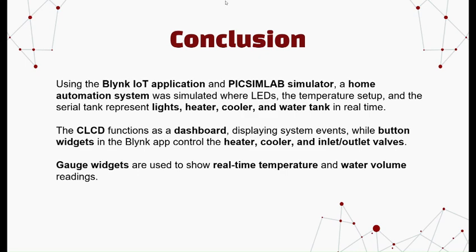And by the way, the conclusion is using the Blynk IoT application and PICSimLab simulator, a home automation system was simulated where LEDs, the temperature setup, and the virtual tank represent lights, heater, cooler, and water tank in real time. The LCD functions as a dashboard, displaying system events, while button widgets in the Blynk app control the heater, cooler, and inlet outlet valves. Gauge widgets are used to show real-time temperature and water volume readings.